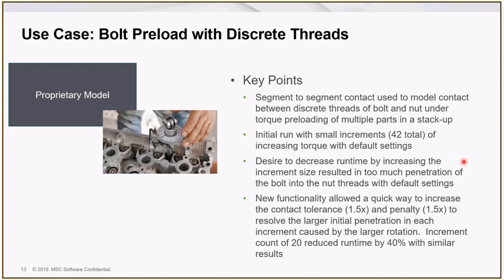And one of the common ways of doing that is to increase the increment size. Now, just a word of caution: this is the first thought that everyone has, and it's a good thought, but sometimes you do have to be careful, because decreasing the runtime by making increments larger can simply result in more iterations in the larger increments, and that can really take away some of the benefit.